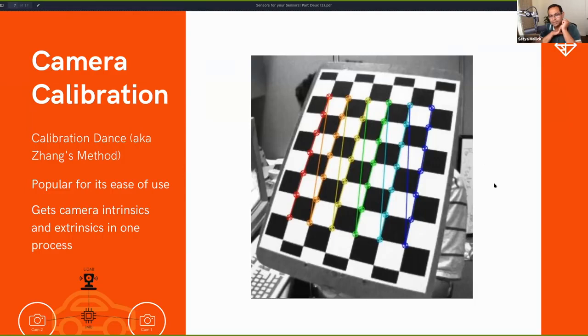Right. And I mean, if you're trying to build something industrial, I would advise that you also look at the Charuco pattern, where the black regions are replaced with ArUco kind of markers. And so that pattern is more stable. It produces better results. And if you want to do something cool, you can also use the circular patterns that are also part of OpenCV. That looks very cool: oh, you're not using a checkerboard, look, I'm using these circles. And it works very well as well. So those are the two things that you can check out.